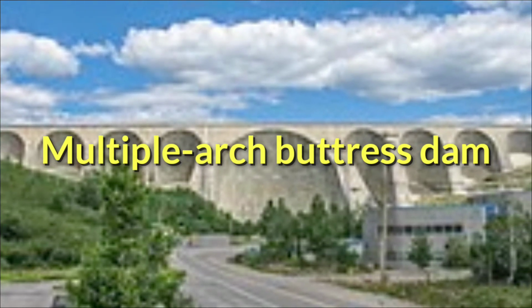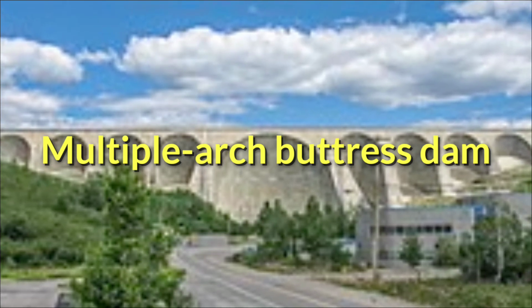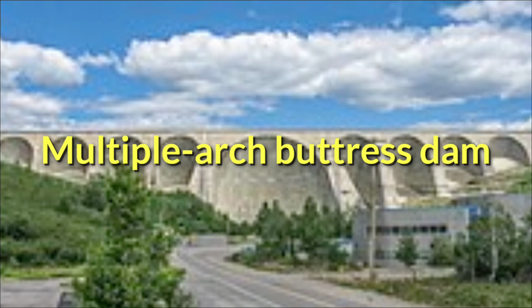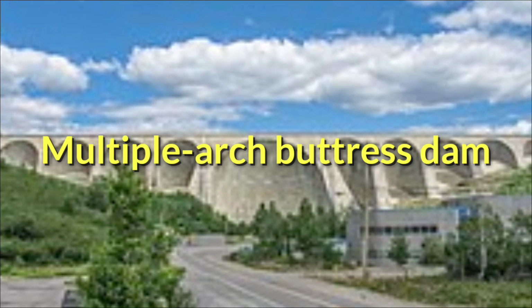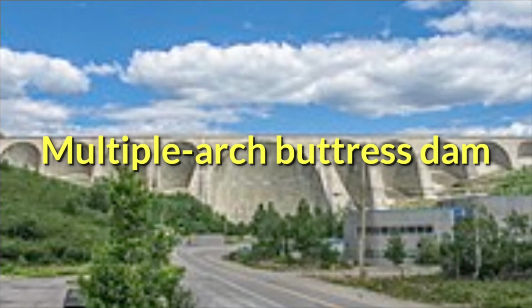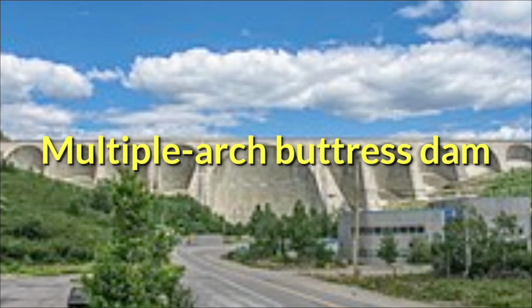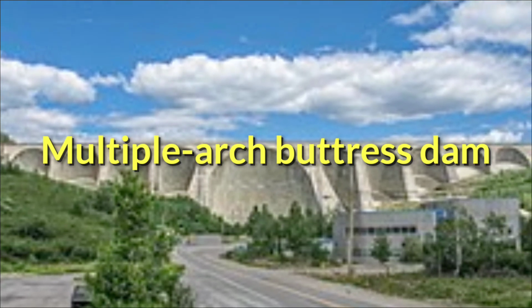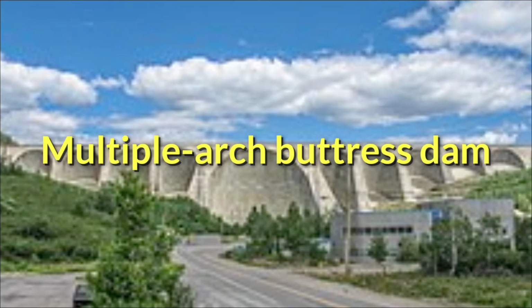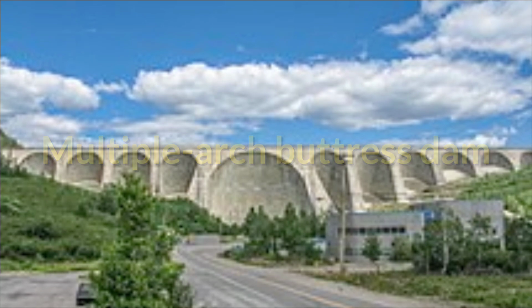On the other hand, a multiple arch dam consists of a number of single arch dams with concrete buttresses as supporting abutments. For example, Daniel Johnson Dam in Canada is the best multiple arch dam. Multiple arch dams do not require as many buttresses as hollow gravity types, but they require a good rock foundation because the buttress loads are very heavy.